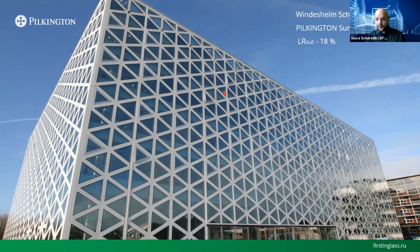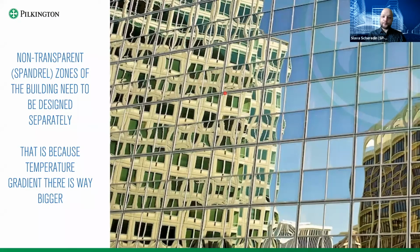The thing is that we have designed transparent zones and non-transparent zones, chosen the color for enameled glass, then went ahead, and in the end we may find that the IG units, which have the very same composition for transparent and non-transparent zones and should look similar on the facade, in fact are not.